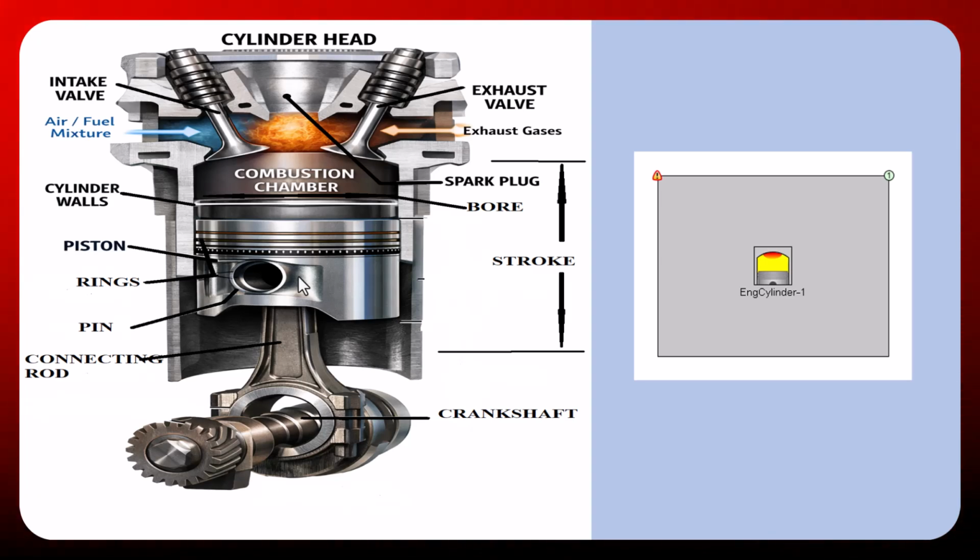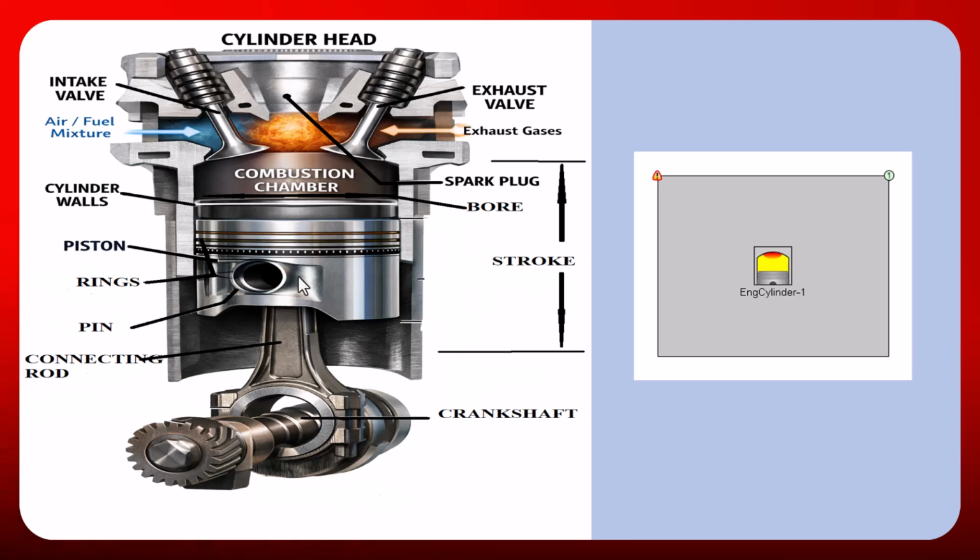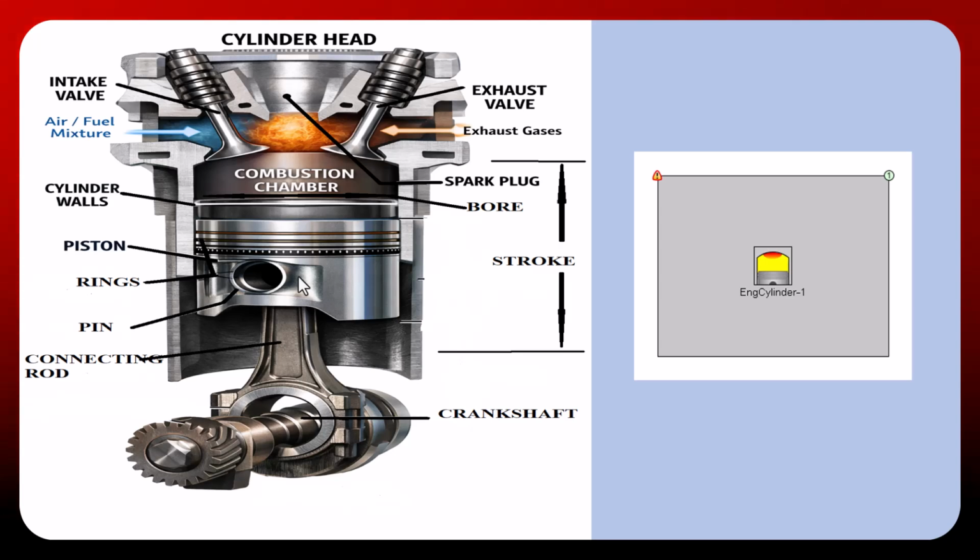On the left side we have the intake valve. The intake valve allows the air or air-fuel mixture to enter the combustion chamber. It opens during the intake stroke, controlled by the camshaft. Its timing strongly affects volumetric efficiency.